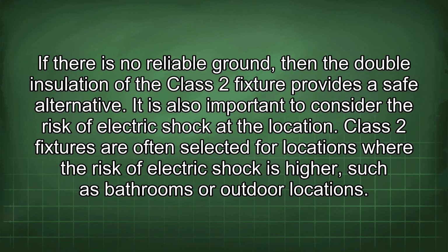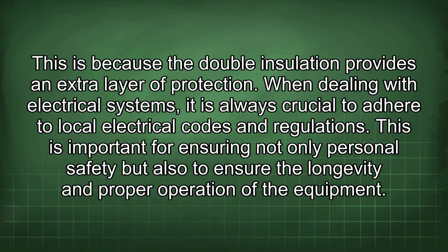It is also important to consider the risk of electric shock at the location. Class 2 fixtures are often selected for locations where the risk of electric shock is higher, such as bathrooms or outdoor locations. This is because the double insulation provides an extra layer of protection.